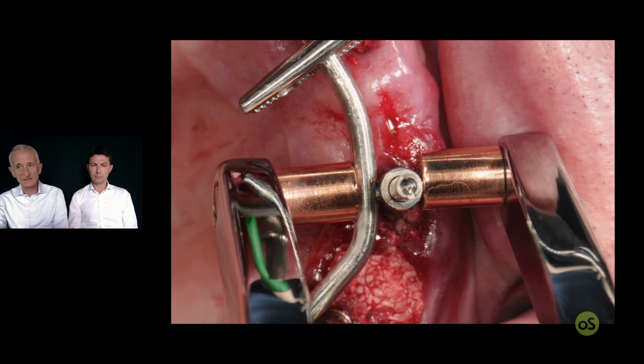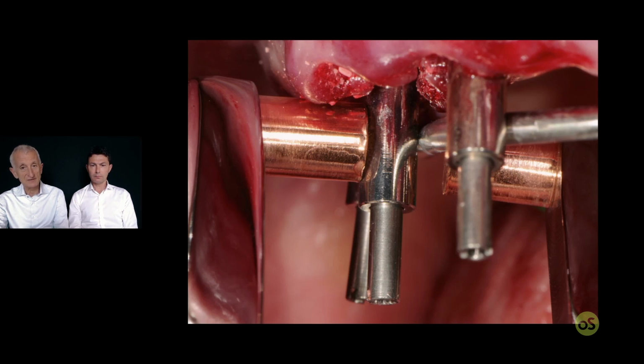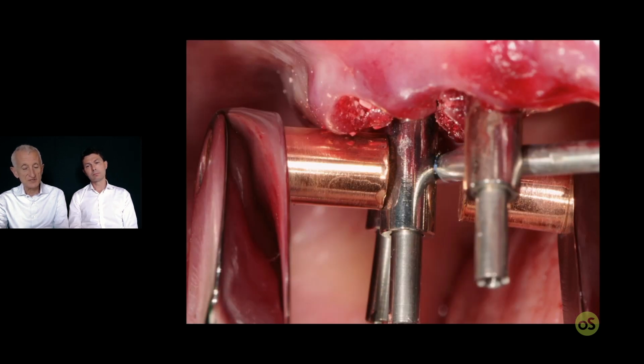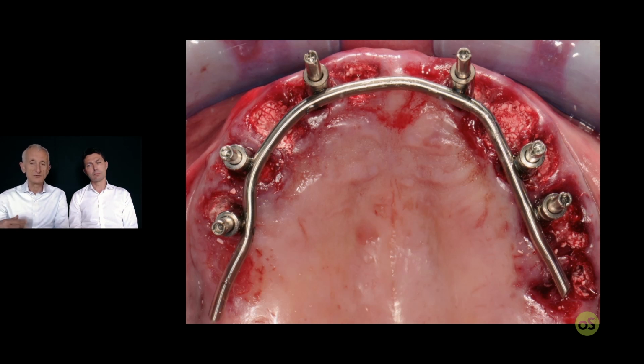And after the electricity has been released, it is preferred to wait 3 seconds to let the heating disappear through the clamp. So you wait 3 seconds, or you ask someone of your staff just to spray some cold water immediately after the welding. So you repeat the procedure, moving to the next contiguous cylinder.